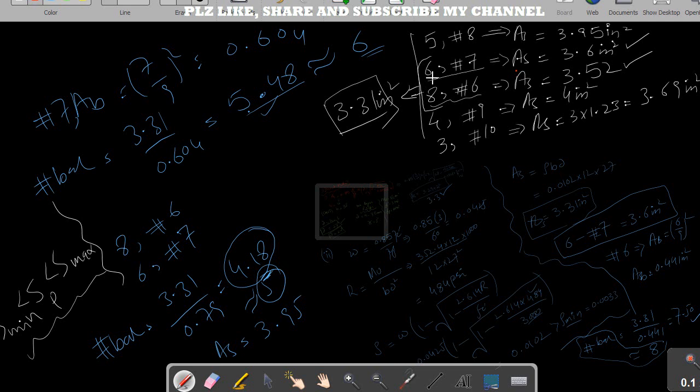So that's why I always choose one size bar, right? We can choose two size bars as in the previous part, which is in case 1 where we chose a different combination, right? We chose 3 number 8 and 3 number 7 bar in the previous case, but this time the best option is this one, right? Because this is close to the calculated value 3.31 square inches, and this option is the second best one.